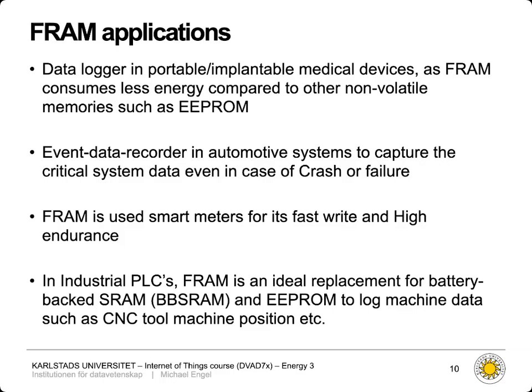So FRAM seems to be one of the most promising technologies out there, and it's already available in some devices. So FRAM is great because it just is relatively energy efficient, it's relatively low cost, and so it can have a number of interesting applications. For example, you could use it to log data in portable or even implantable medical devices because of its low energy consumption compared to all the other sorts of non-volatile memories such as EEPROM, and you don't have to take it out to replace it because FRAM has a very high number of write cycles.